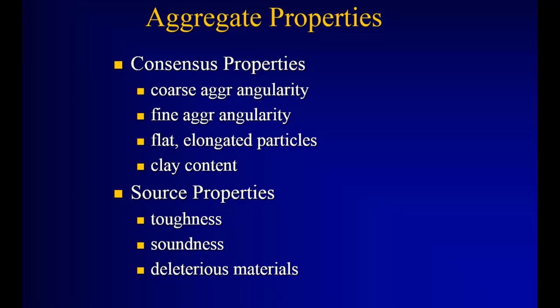Most field labs at one time had the old Los Angeles abrasion drum in it. And basically you throw all your +10 or +12 coarse aggregate into there with a couple ball bearings, these big ball bearings, and turn it on, and it's rotating like your dryer at home. It's like throwing 8 pairs of tennis shoes in your dryer and watching them pound around, but in this case you put steel ball bearings to knock the aggregate down. So we've had that for a long time.